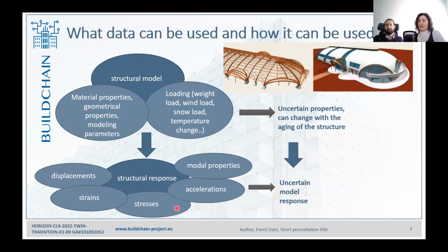With a conventional design process, what I would need to check is the worst scenario, what could be the load on the structure, and the worst scenario for my material properties, as bad as could happen. And then I want to see that the biggest stresses in the structure will not be bigger than what the material can resist.